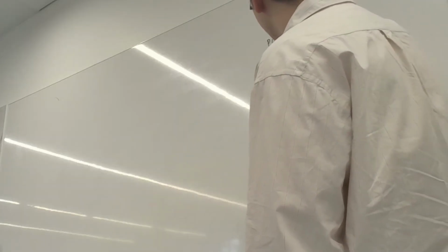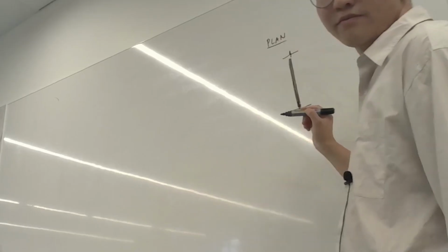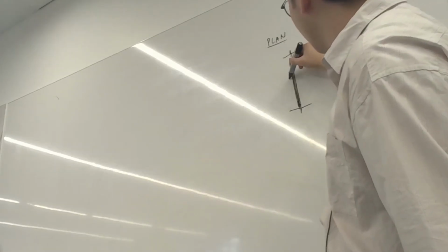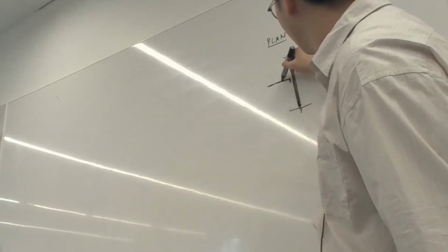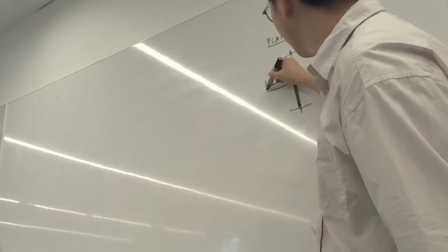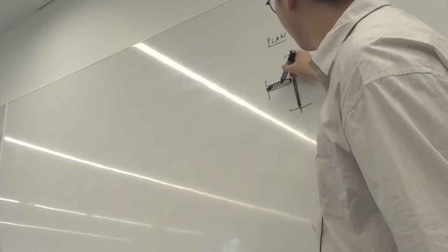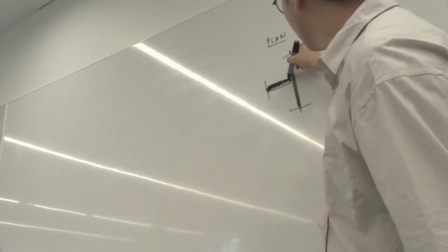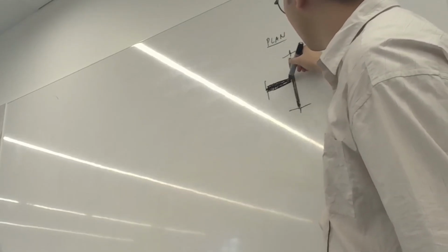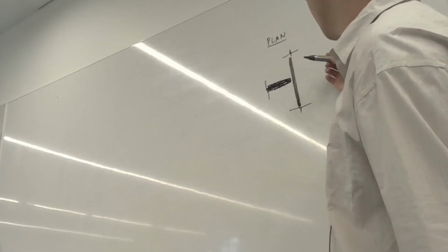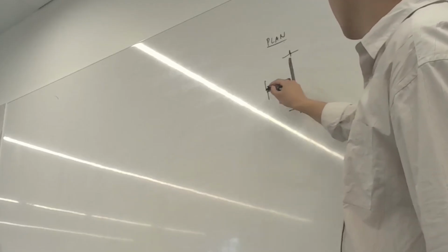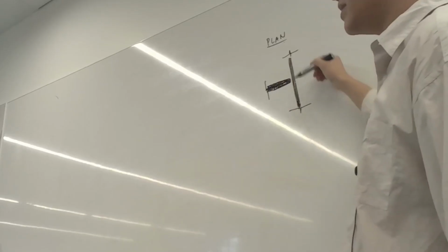So normally, in engineering drawings, if you do a thick line in plan view, that refers to a steel beam, depending on how much detail you want to draw. You've got a thick line, and then coming off of it, another thick line. So this would be a secondary beam, for example. I've drawn it so that the secondary beam looks chunkier than the primary beam, which could be the case sometimes, but maybe I should have drawn it so that this one was thicker. But this is the notation.